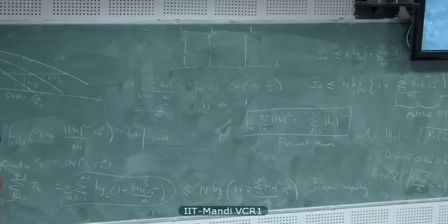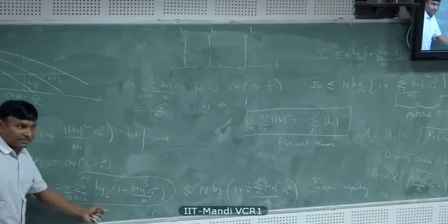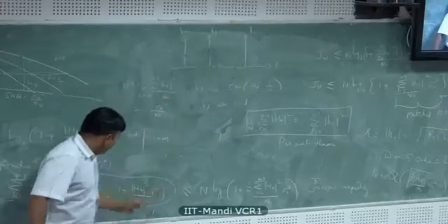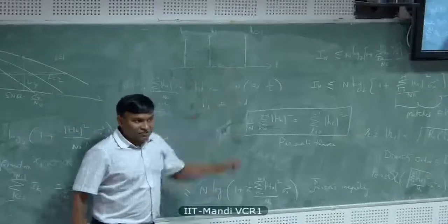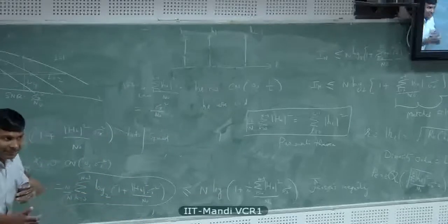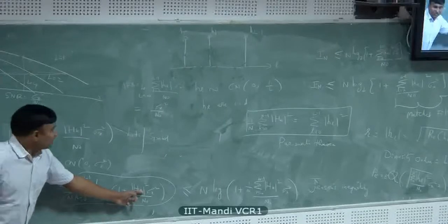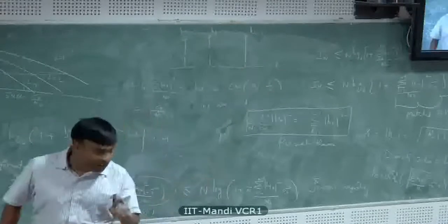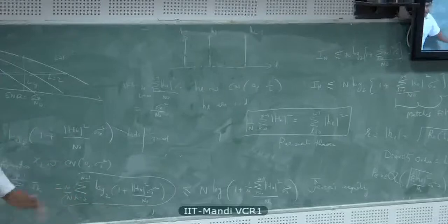So, what channel capacity do we assume for that? This is the mutual information, the capacity of the channel. So if you hit this, you're good, because there is plenty of diversity, and of course, as long as L is a very large number. If L is 1 or 2, then this capacity itself fluctuates a lot because of this H_k, which is not a sum contributed by an infinite number of taps. If you have a single tap channel, this capacity fluctuates.